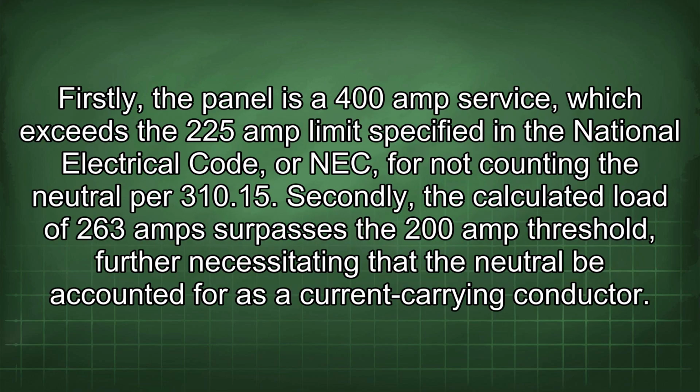Firstly, the panel is a 400 amp service which exceeds the 225 amp limit specified in the National Electrical Code, or NEC, for not counting the neutral per 310.15. Secondly, the calculated load of 263 amps surpasses the 200 amp threshold, further necessitating that the neutral be accounted for as a current carrying conductor.